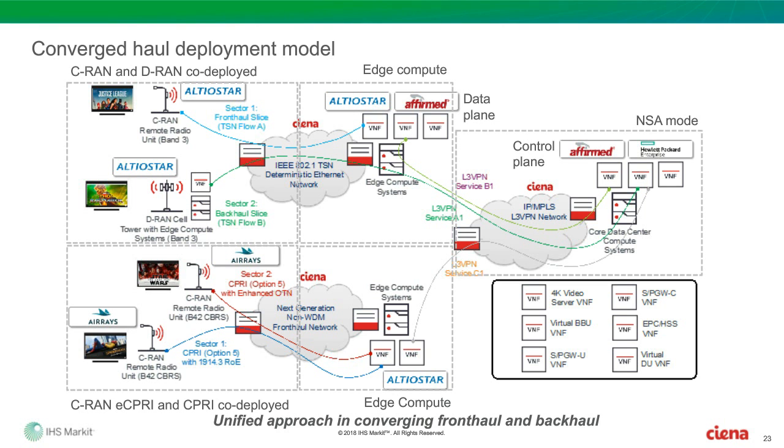And it's important that you build a network where you can share those transport level and drive the right economics behind it. And that's basically what we are demonstrating here on the top left side, where the TSN technologies truly shine, where you get the statistical multiplexing gain and you deliver on the tight characteristics of the CPRI signal while still enabling the transport of the backhaul system. Different deployment scenarios will drive different selection of technologies, and here we believe that TSN brings a lot of value in the access by enabling this mixed traffic scenario.